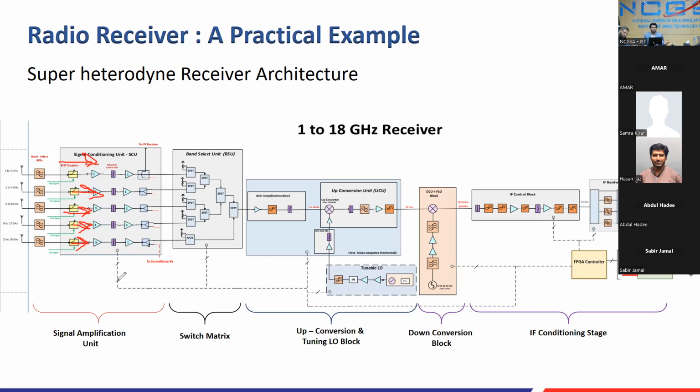You need to test that. So built-in test couplers, you should actually have in any receiver or any model you are making. So you can have a built-in test signal for this application. You can get the signal from this part to test the receiver gain parameters, noise figure, noise floor, inputting a known signal. In addition to that, what you can actually use built-in test signal for RSS estimation.